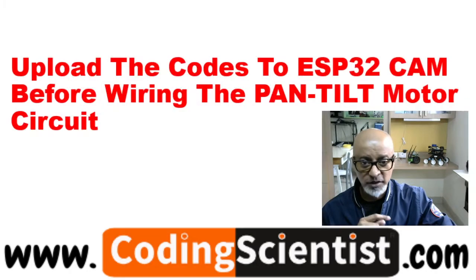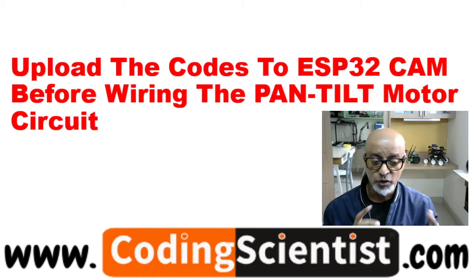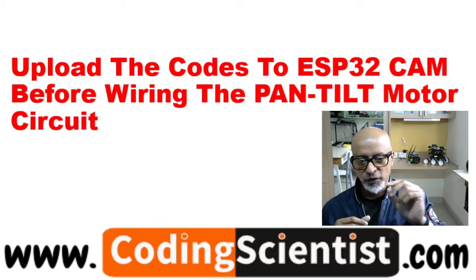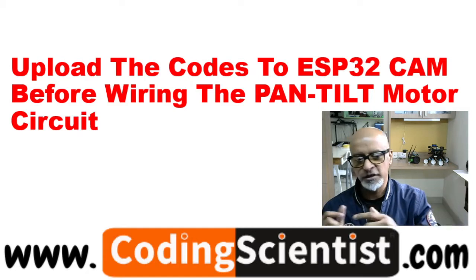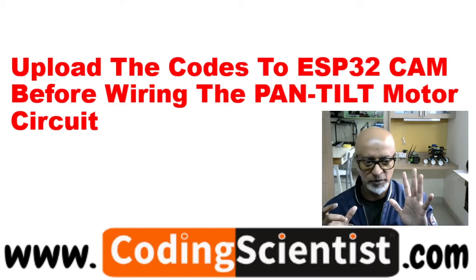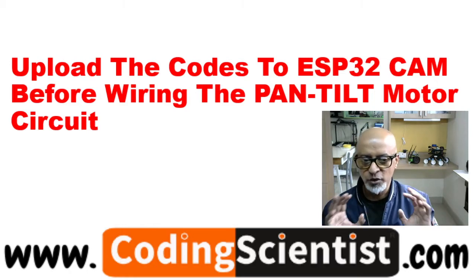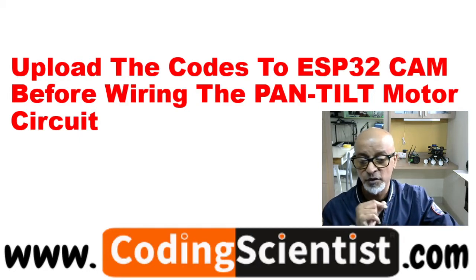And then the next step: upload the code to the ESP32 CAM before you start wiring your pan and tilt motors, the two SG90 motors. Before even starting to build the circuit, first upload the code and then open the serial monitor, look for the IP address, and then open a browser, put in that IP address and see if the video is streaming. You will see four different buttons, right? Nothing else. And then you unplug, disconnect everything. Do not do anything else, just disconnect. Make sure that you upload the code before building the circuit.